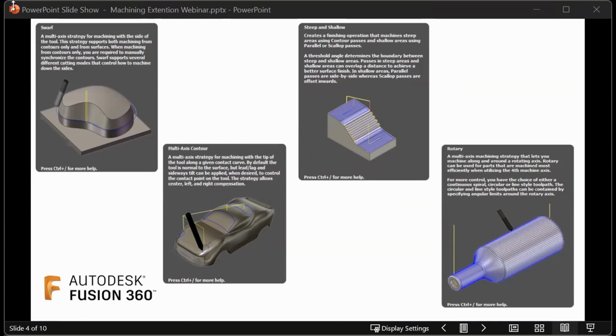It's a very good finishing strategy for a lot of parts, especially organic parts that have deep radiuses, deep fillets. It kind of uses the center point of your tool and gives you much better, nicer finishes in those tiny edges across your part. It gives you the ability to blend features between your walls and your floors.